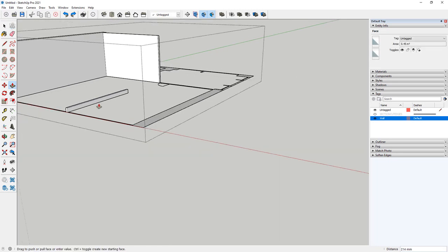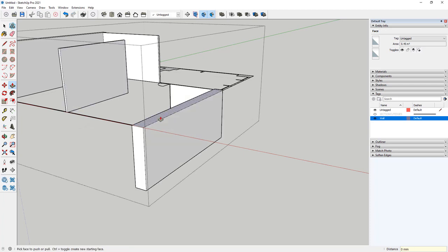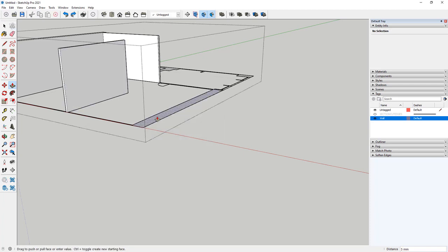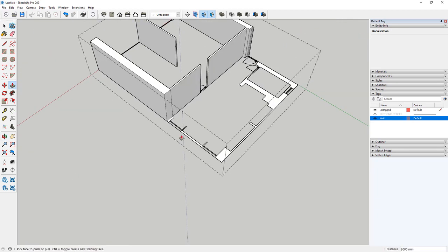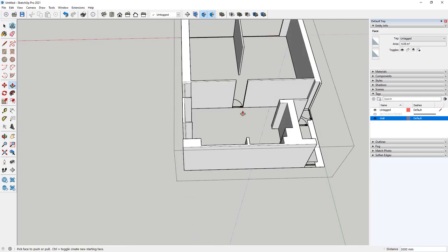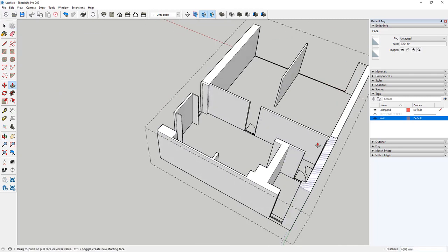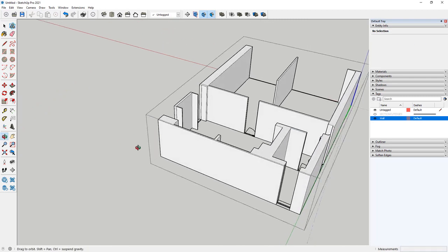This is also a very common problem. So in this situation the best solution will be to use manual extrude and set the distance with the keyboard, or you can use the mouse and try to put them at the same height for each side.